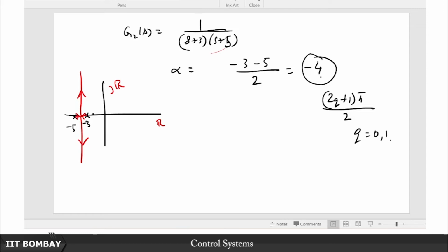and here is why it is important. Now note that if I hadn't told you this centroid location, then for a system like this, where the two poles are here and here, you would still draw the asymptote from the origin, and for a system such as this, which is the one I have just drawn here, you would still draw the asymptote like this.